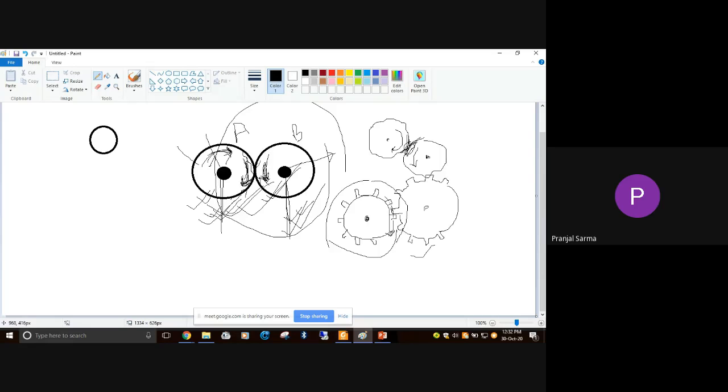There will be some circles with respect to which we'll be able to define things. The contact will be at the pitch point, or if we discuss the circle, it becomes the pitch circle. So ultimately the discussion of gears can be done in an easy manner with reference to this particular circle. That's why later, whenever we are discussing gears, you'll see that sometimes we may even draw the gears like this, but actually the gears have teeth on the periphery. You must understand that it is only for easy analysis purposes that we are drawing like this.